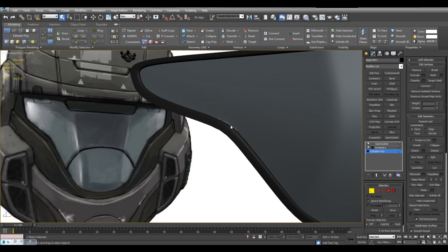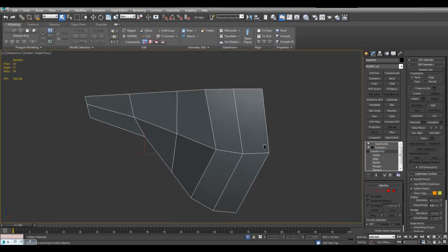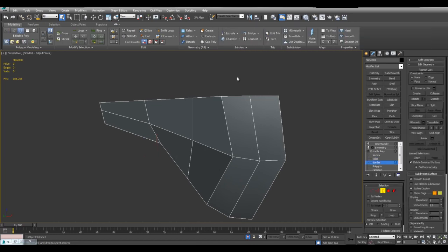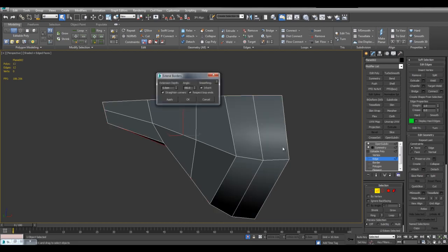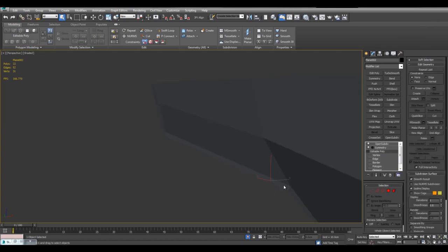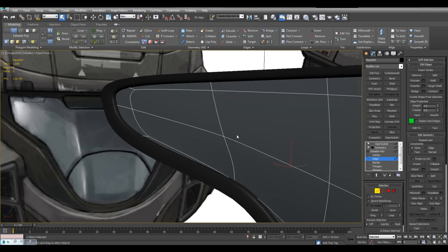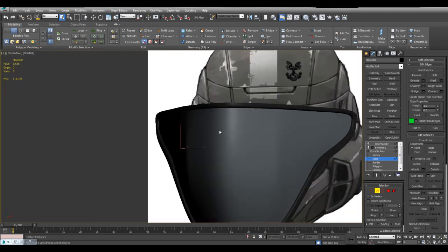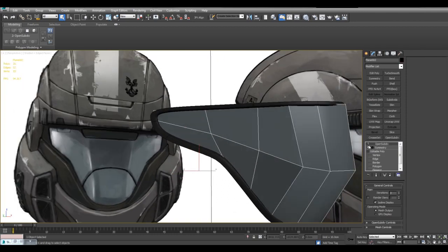Now you'll notice that right here there's a little bit of a gap in the visor. So what I can do is do the same thing that I did previously. Switch to border, select, 2, hold Alt, deselect, apply the script, but this time just set the angle to 0 and just set the extension depth to a little bit, just so we no longer have that effect. And now you notice there's no longer a gap here because we moved the visor just a little bit past it.